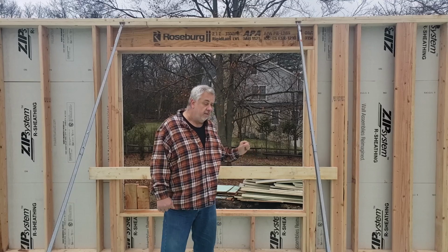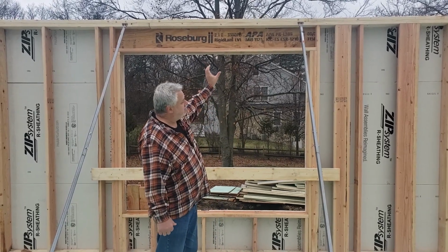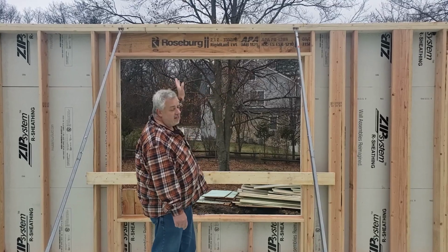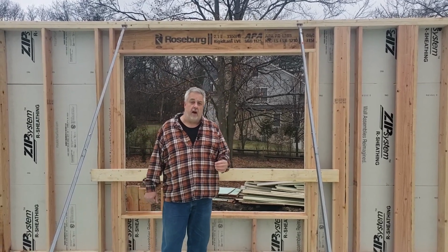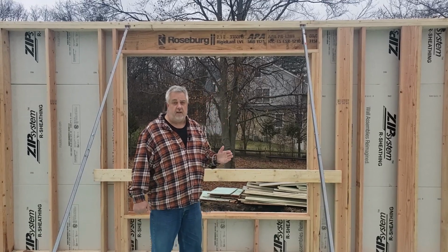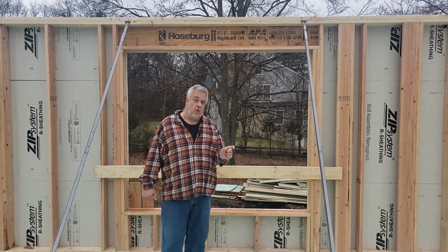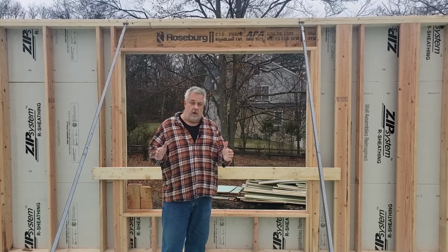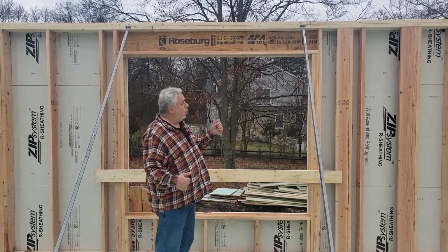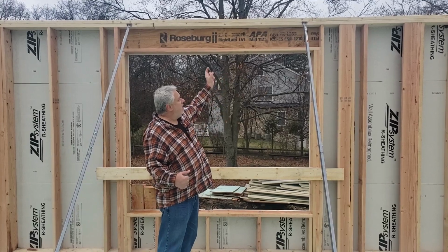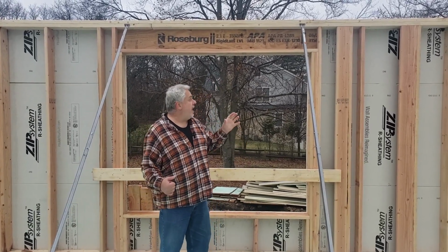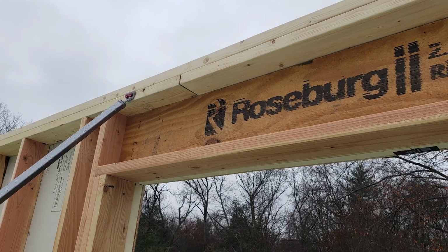Now, the beauty of pushing the header tight up to the top plate is I can pick, in this case, a 9.5-inch LVL as my header system. And because I have 5.5 inches, and those headers are 1 3/4, in the narrower windows, I just do a single ply. So I do 1 3/4. In some of the wider windows, like here, this actually gets a 2-ply, so we have 2 headers up there. And so the pocket is a little bit shallower.